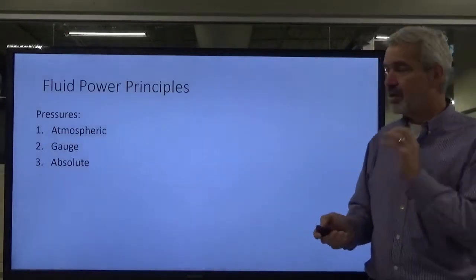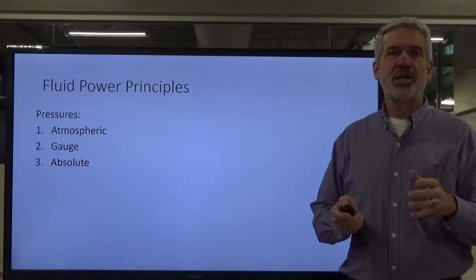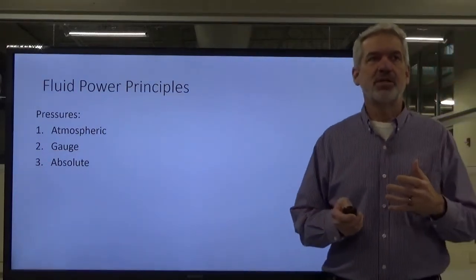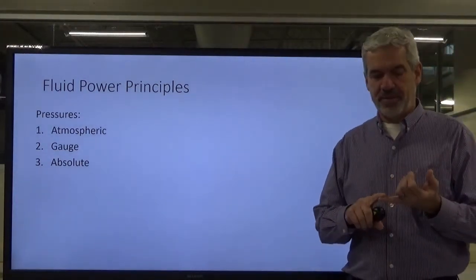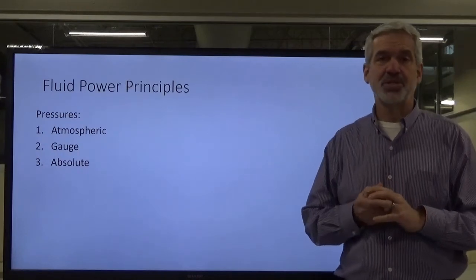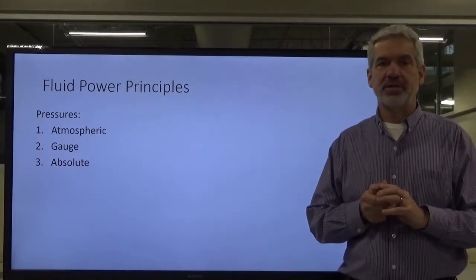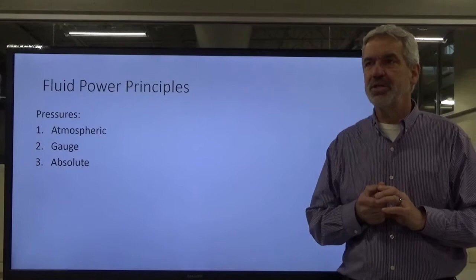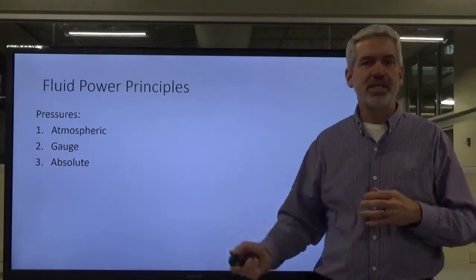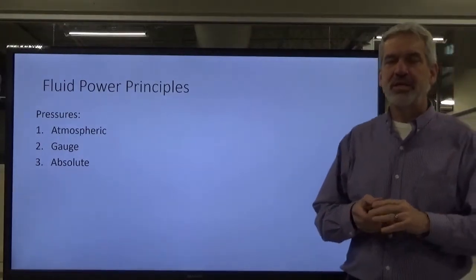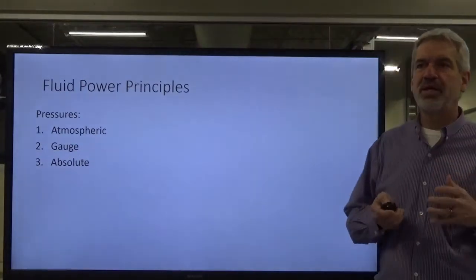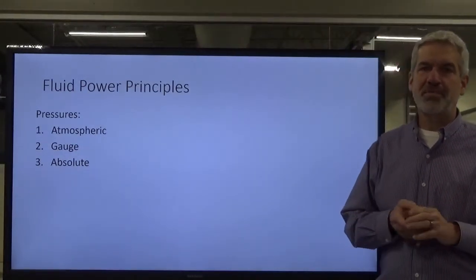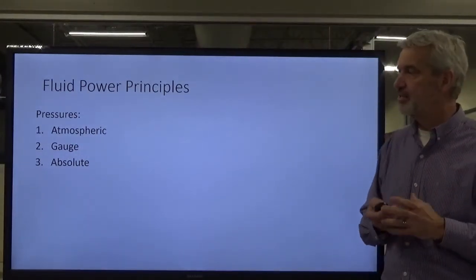Very quickly, I want to talk about gauges. They're kind of important because gauges help us learn about the health of the machine. Also, if you're troubleshooting, if you don't have enough pressure, what's going on? Are we losing pressure? Do we have ample pressure? If you've got ample pressure, then we need to start looking elsewhere, okay? So it gives us an idea of what our pump is doing. Are we delivering the proper amount of pressure and flow to the devices to make them work?